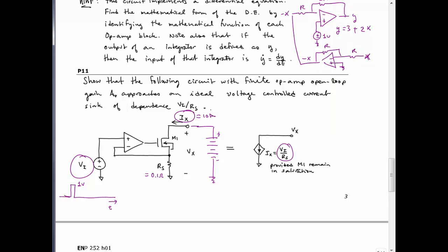All right, let's say that's what I want to do. I want to test the battery at 10 amps, not 1 amp. So I give it a little pulse from a function generator. It lasts maybe a millisecond, and I pulse it to 1 volt. And what has this circuit done? It's converted my little voltage into a very accurate current sink. It pulls current from the battery, and it's actually absorbing power.